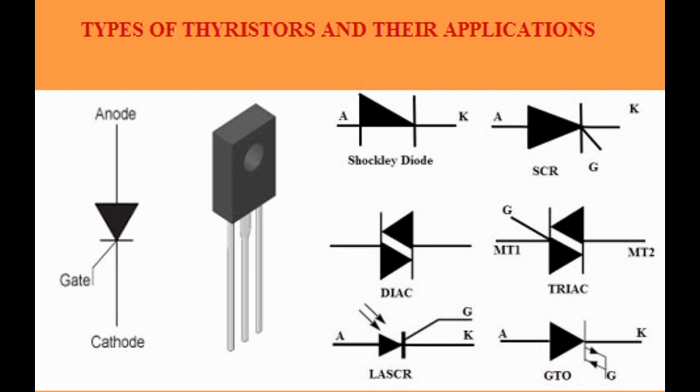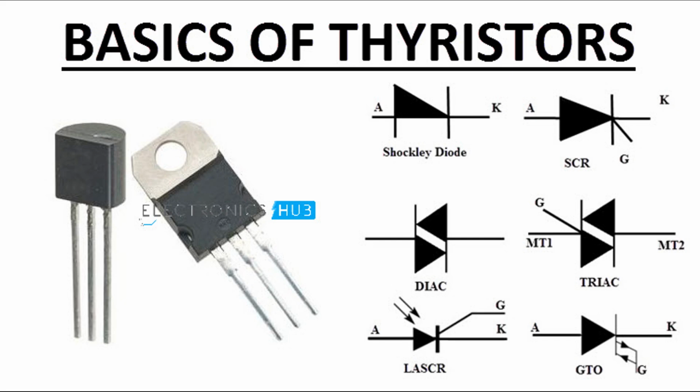Example application: high-power industrial motor drive. In a high-power industrial motor drive application, the IGCT can be used as follows. Initial state: the IGCT is in the off state, blocking current flow. Turn-on pulse: a high current pulse is applied to the gate, turning on the IGCT and allowing current to flow to the motor. Current flow: the IGCT conducts, providing power to the motor and controlling its operation. Turn-off pulse: a reverse gate current is applied to turn off the IGCT, stopping the current flow to the motor. Control: the gate drive circuit continuously monitors and adjusts the gate signals to control the motor's speed and torque precisely.